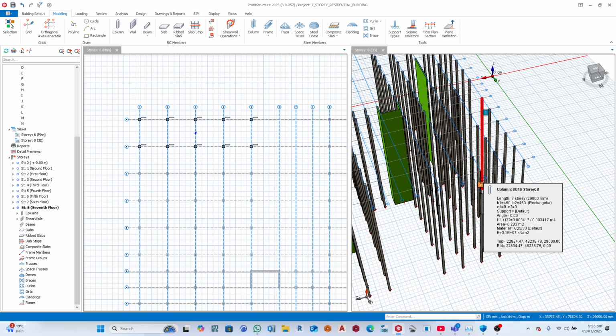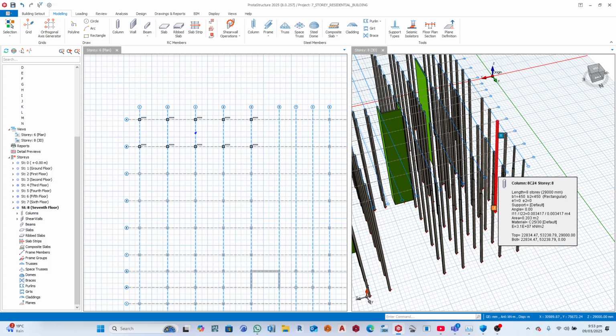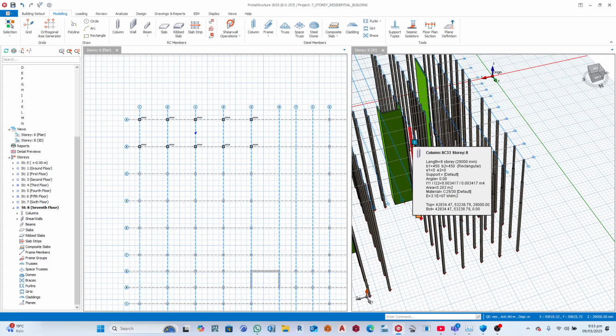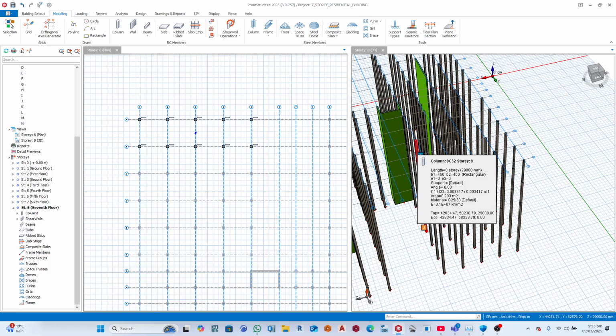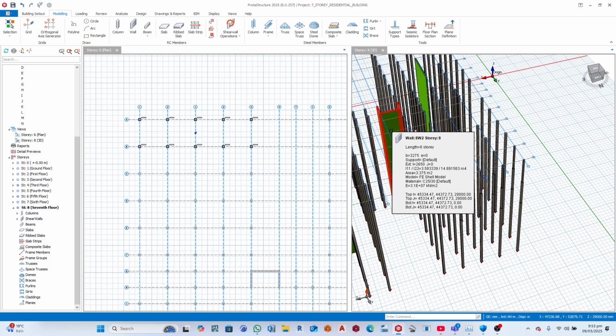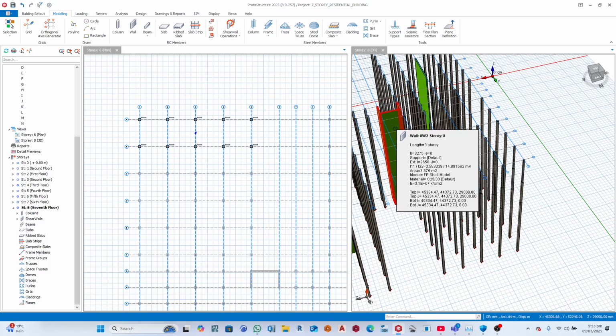So that's why there's that concept where we say the column should be able to carry whatever it's carrying and just transmit it down without it being affected by whatever has been imposed on it. So the resistance should be more than the loading, so that it doesn't fail. Because the moment it fails, we have to pray that there's some redundancy somewhere. Redundancy being one member in a structure can fail without jeopardizing the entire structure.